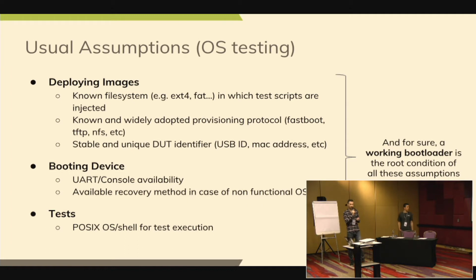For booting the device, you need a UART debug console, because you need to check the output of the console to see whether the device has correctly booted or not. And you want to use this console as well to log in to the device, to run the test, and also to pass the test results.